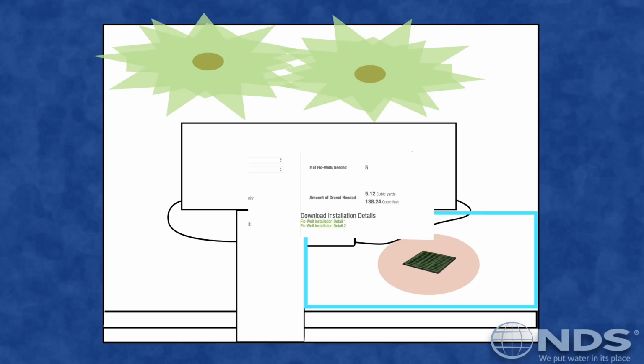In practice, it is rarely required to provide the full detention volume for a 25-year, 30-minute rain event. Check your local regulations for guidance on runoff detention requirements.